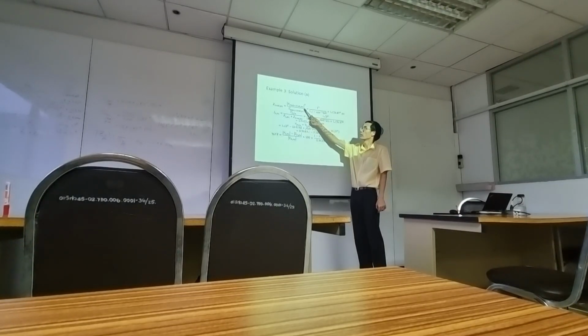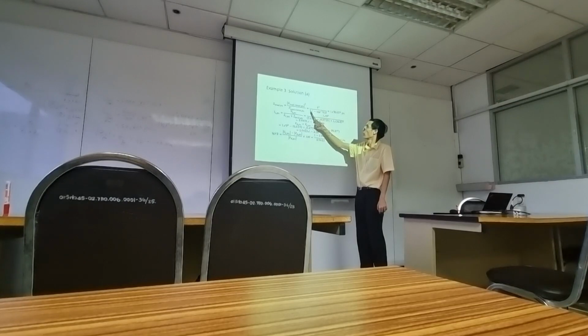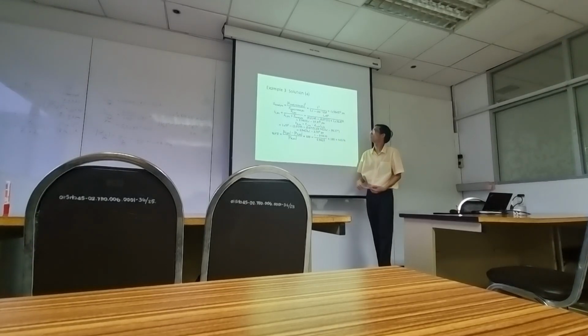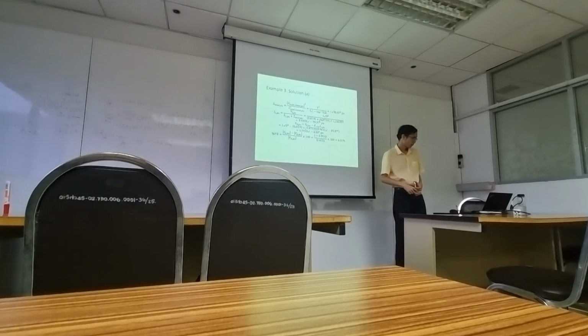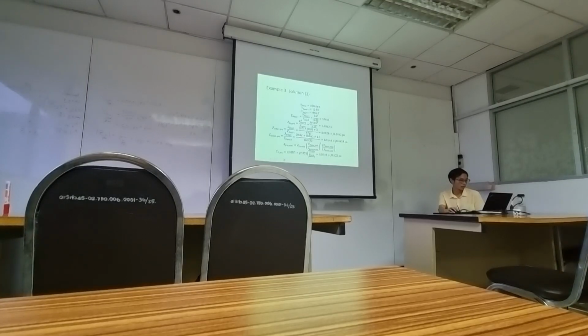This voltage in per unit is 1, divided by 1 angle minus phi. Do you know why the load voltage V load is 1 per unit? You can see that the load voltage is 416 volt, and the base is also 416.